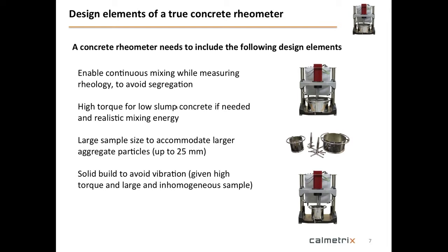What we would want is, first of all, the ability for continuous mixing while we measure rheology. So we can avoid segregation and we can see continuously what happens while we mix, and as the concrete is in a state where it would normally be between the time it is batched and the time it is delivered to the site, or the time it is batched and the time it is put in the forms.